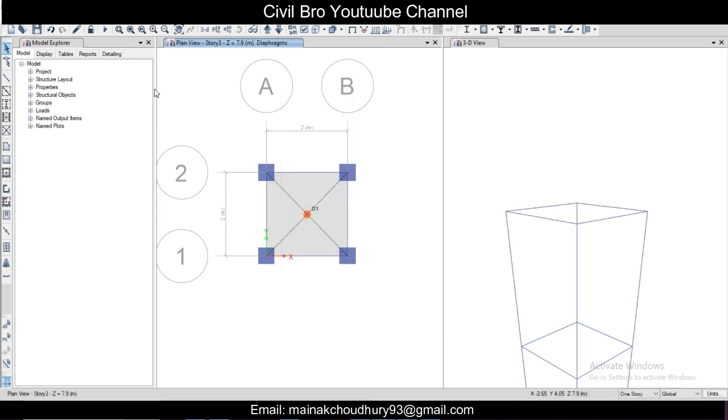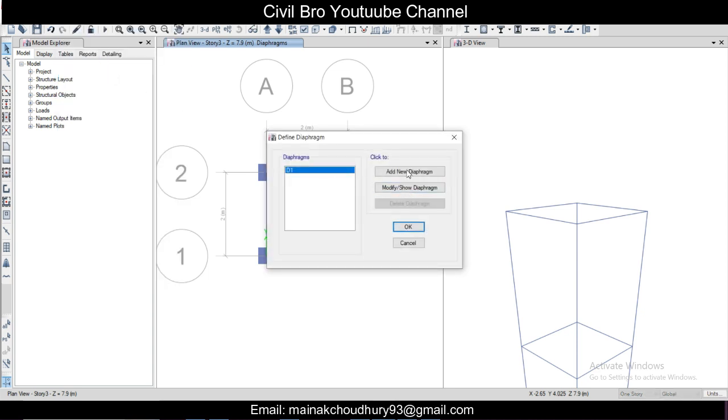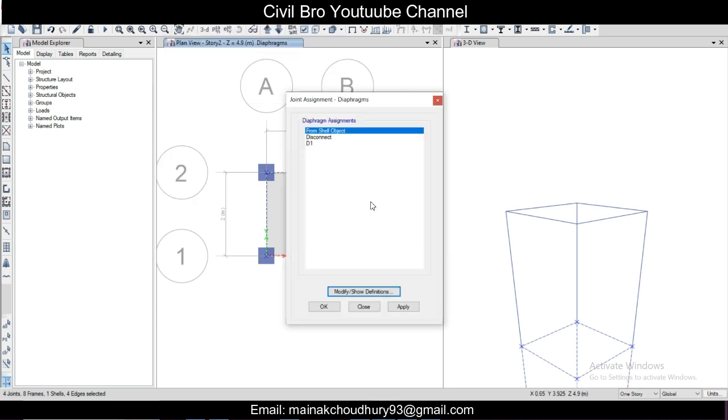Okay, and go to define diaphragms, add new diaphragm, D2, and we'll assign it a level below.